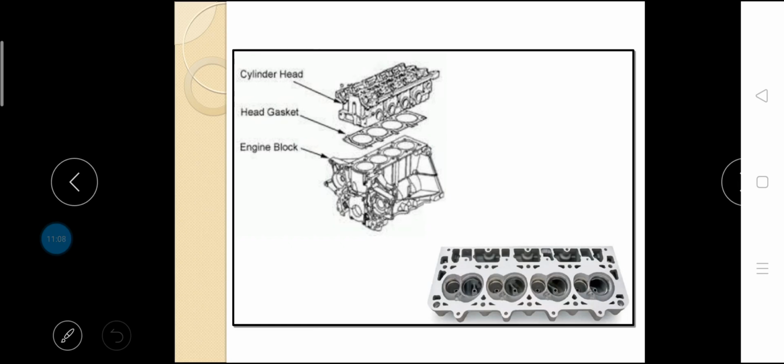However, for certain heavy-duty engines such as in racing cars, where the cool running of the engines is a major consideration, the use of copper alloys as cylinder head material has achieved much success. The thermal conductivity of these copper alloys is approximately twice that of aluminum and 6 times that of cast iron. Because of this, the engine tends to run cooler and consequently higher compression ratios can be employed without occurrence of detonation.